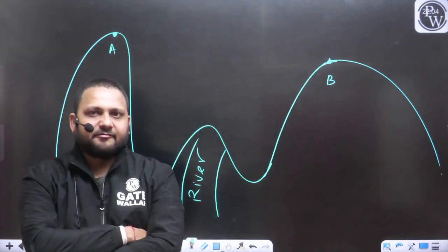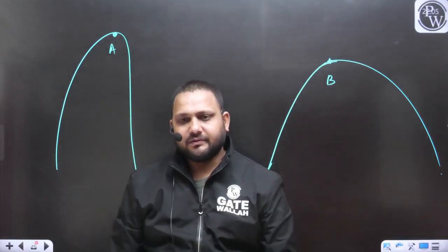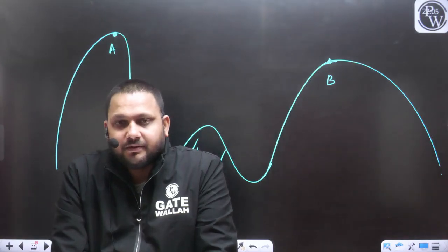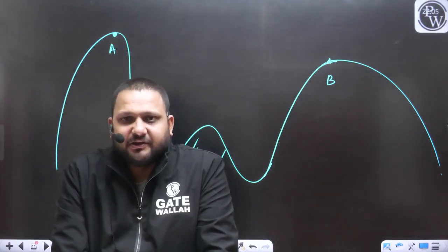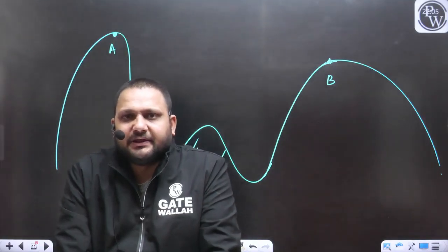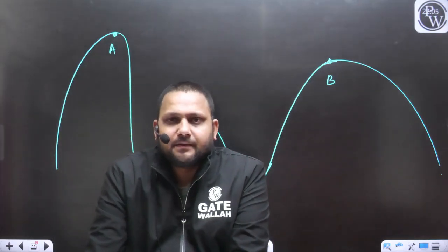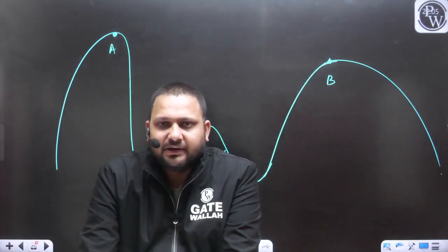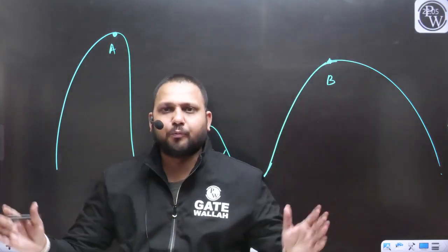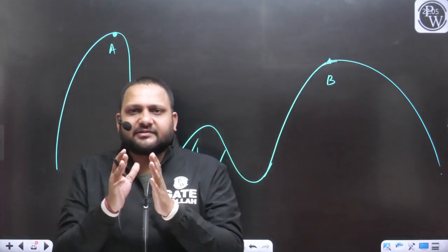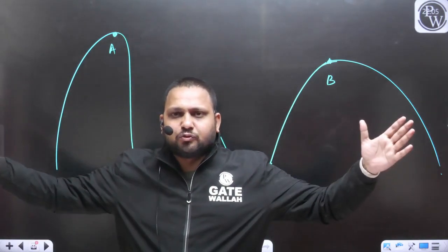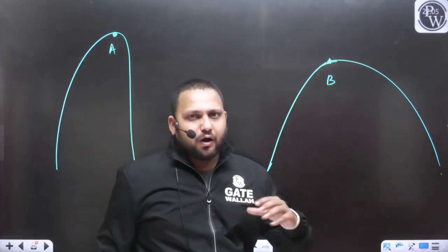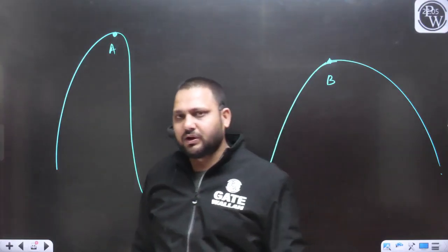We have just discussed, sir, if the 2 points are A and B, yes, this is geodetic leveling. Geodetic leveling means when you are considering the effect of the curvature. The error will be there due to the distance between the point A and B. That error will not depend upon the method. Error will depend upon the distance between these 2 points. If the distance between these 2 points is less, there will be less error. If the distance is more, there will be more error. So it is not dependent upon the HI method, the rise and fall method, or the reciprocal leveling method, yes or no?